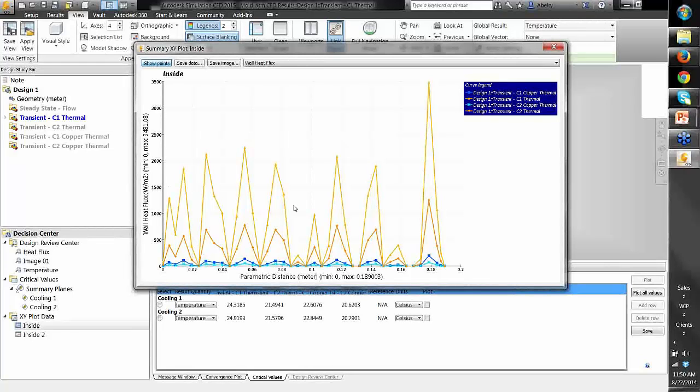We have the first 4 loops, and then this is the middle one where you have the streams crossing back on top of each other. This one actually cools the worst. Seeing something like this, you can probably loosen up the cooling on this side, maybe bring in some cooling in the middle, and try to cool it from the middle outward.